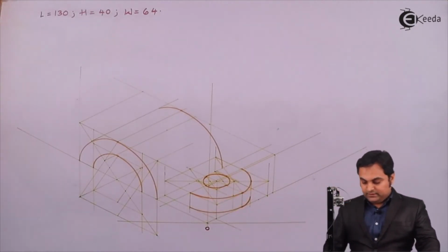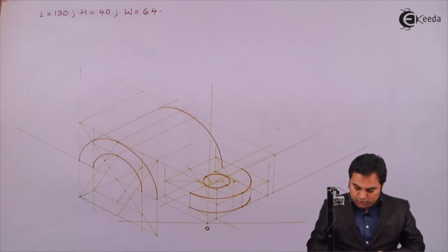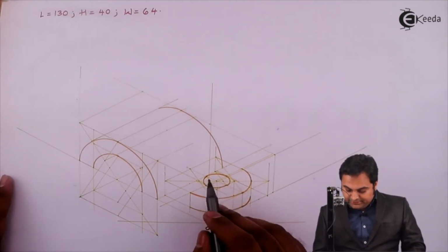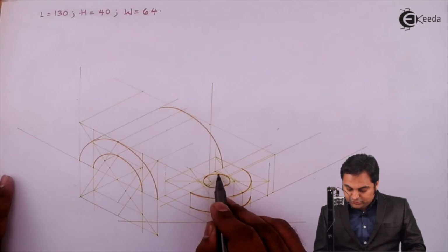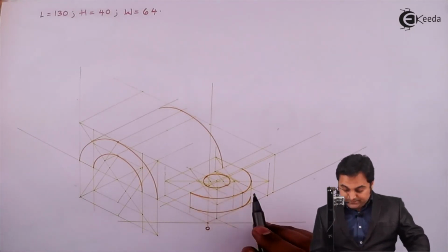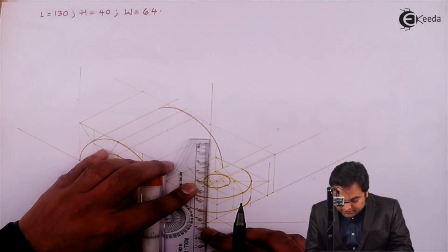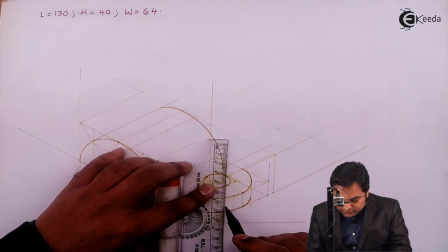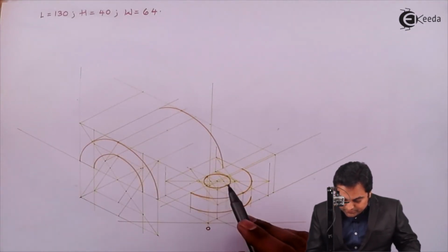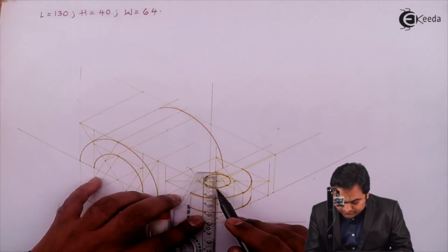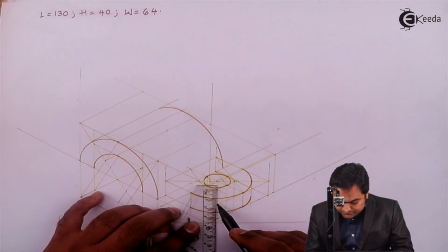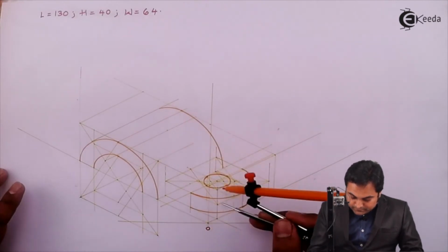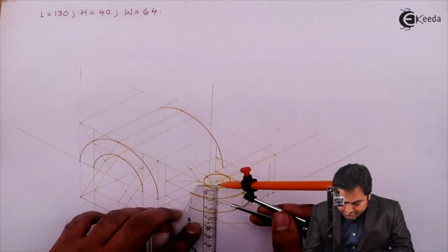Now since it is 15 mm deep, we have to check whether some portion of the circle will be visible inside this. So for that I need an arc here, parallel to this arc. Projecting a light line downwards, and for this arc the center was here, so projecting that center down, measuring 15 mm over it, and I can keep the same radius, but the center is shifted 15 mm down.